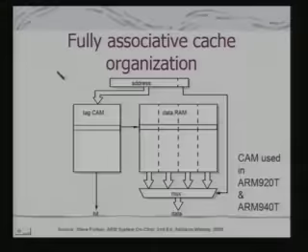In case of CAM, you are just reorganizing the whole RAM, that is your tag RAM as well as your cache. What we are showing here is a combination of both your tag as well as the index together. You can consider this an address going into this tag CAM, which is a content addressable memory.